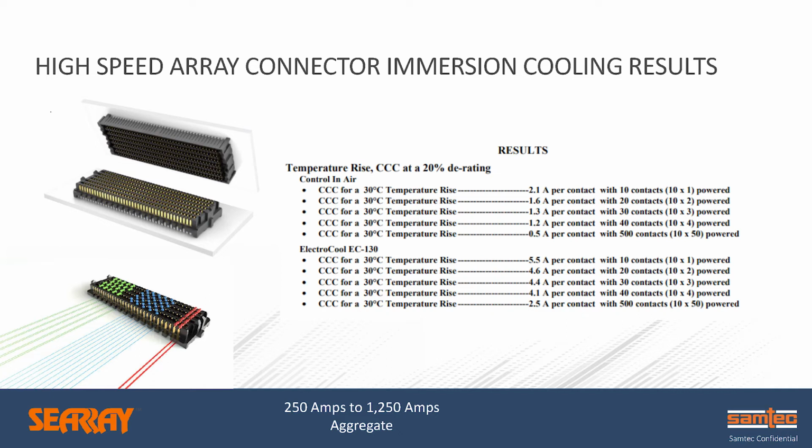Now in immersion cooling, where the connector is mated and in the liquid, we go from 0.5 amps per pin to 2.5 amps per pin. This takes our aggregate amps from 250 to 1250 for the full connector.